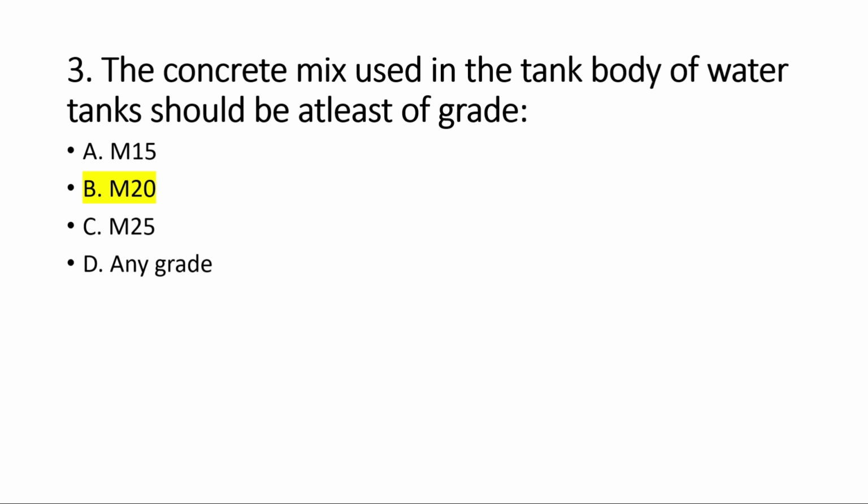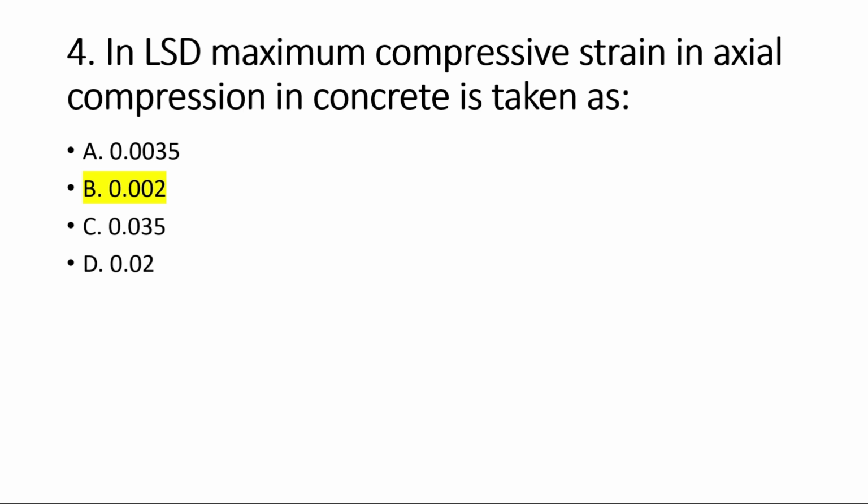Okay, move on to the next question. In the limit state method of design, the maximum compressive strain in axial compression in concrete is taken as 0.002. Okay, so this is again an important question. The maximum compressive strain in axial compression in concrete is taken as 0.002.